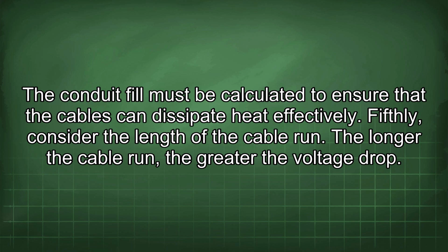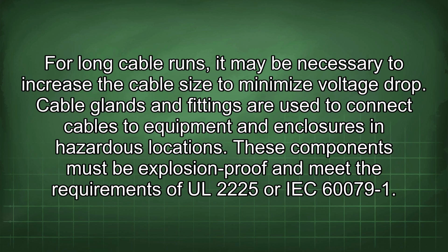Fifthly, consider the length of the cable run. The longer the cable run, the greater the voltage drop. For long cable runs, it may be necessary to increase the cable size to minimize voltage drop.